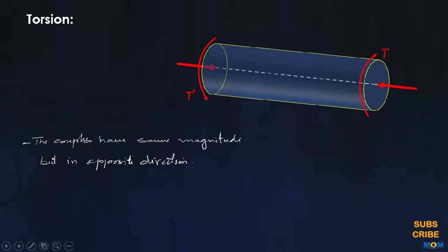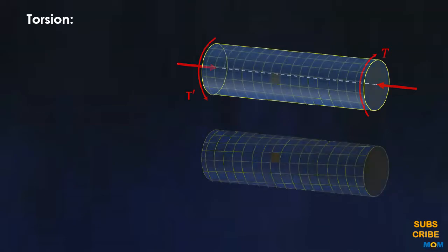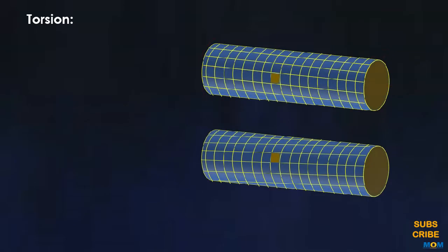The right hand rule may be used to represent the loading. When a circular shaft is subjected to torsion, every cross section remains plane and undistorted, meaning the cross section rotates as a solid rigid slab. This property allows us to determine the distribution of shearing strains in a circular shaft.